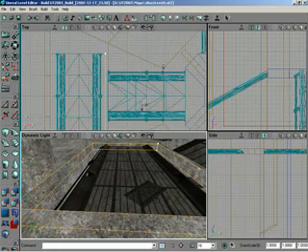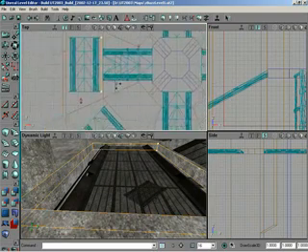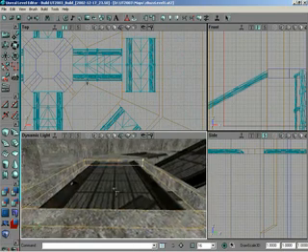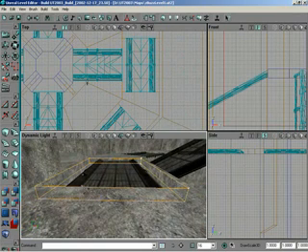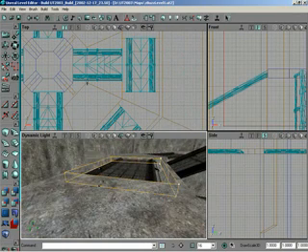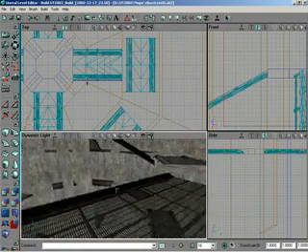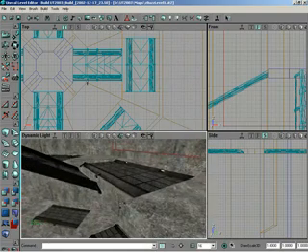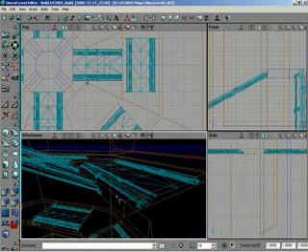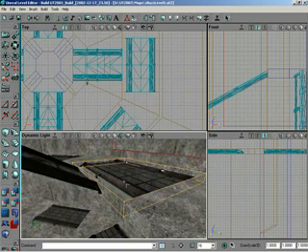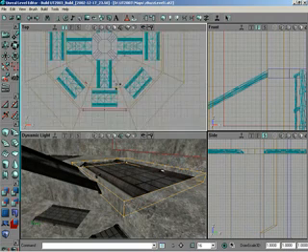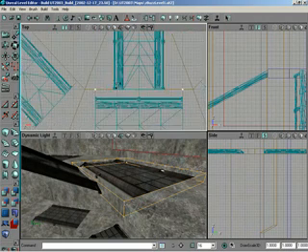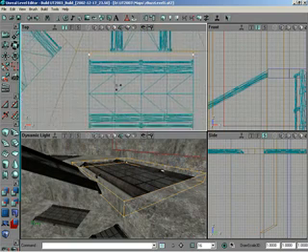So I might just do that all the way around since it's only 4. Just grab those brushes and vertex edit them in. Again, if you wanted, you could use a 368 unit wide cube and then replace all these. Delete them and then resubtract. Okay. So yeah, let's just go ahead and knock out the other sides real quick. So I know that the brush is there, so let me switch over to a perspective wireframe, grab it, go back to shaded so I can see what I'm doing. Then maybe go from the top view, still in vertex editing mode, Control-Alt, drag over all 4 of those vertices, and then pull them back in 16 units.